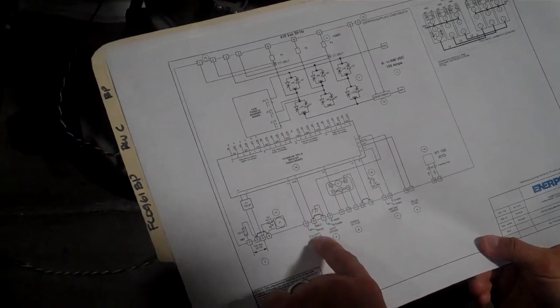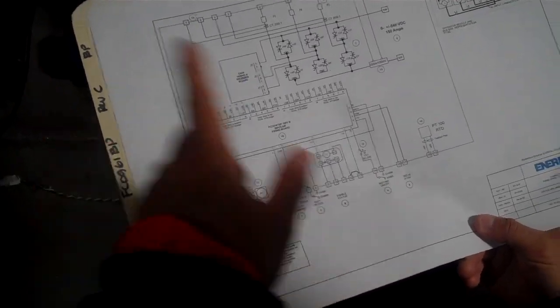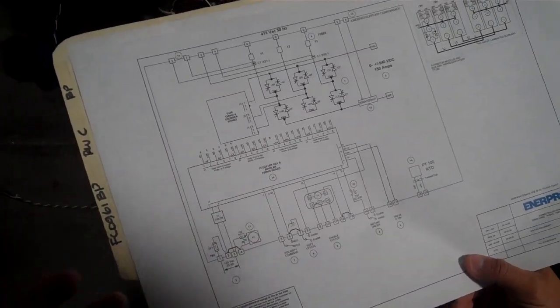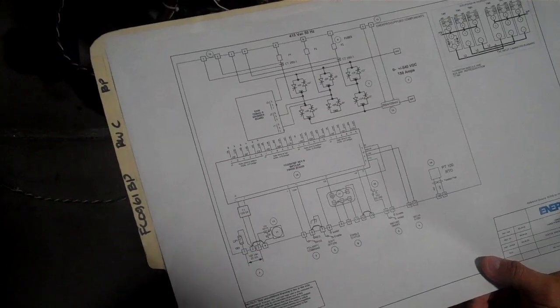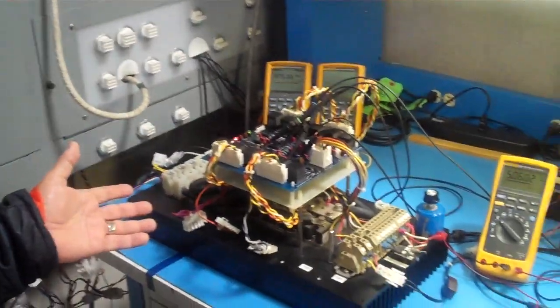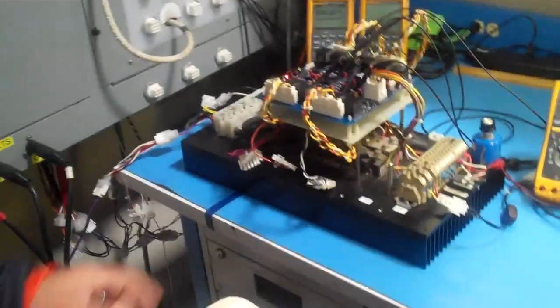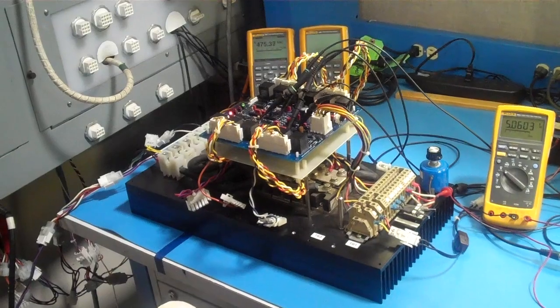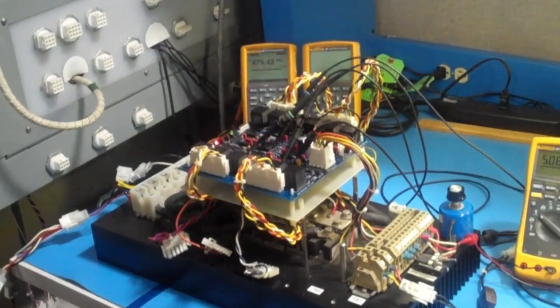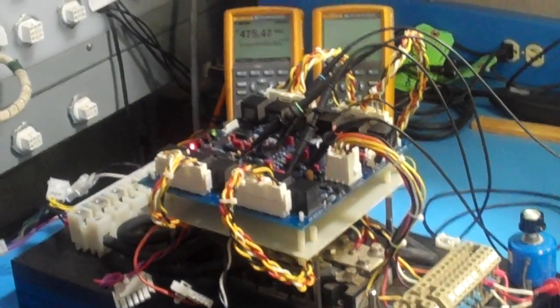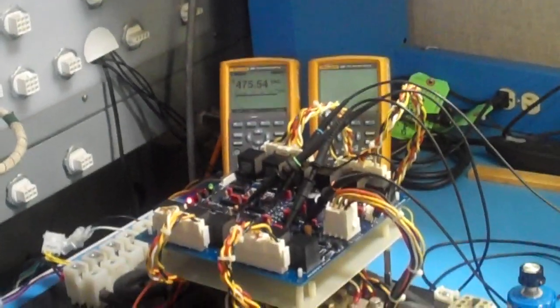We're going to show what happens, how we control the polarity command, and what happens to the output and how fast you get the maximum output. What we have here is a 4 quadrant rectifier. We have 12 SCRs. We have the firing board on top of it, and we're bringing in 480 volts, and the maximum voltage that we're getting is about 610 volts DC.